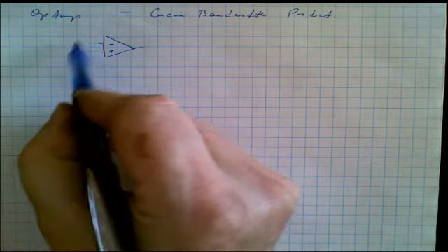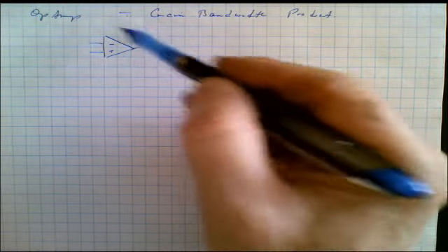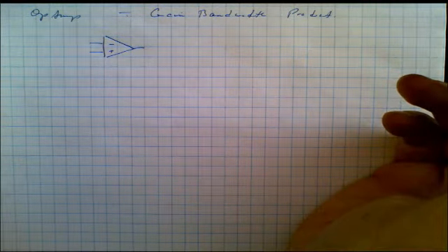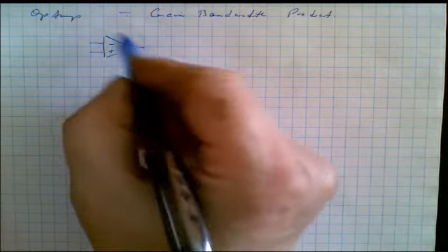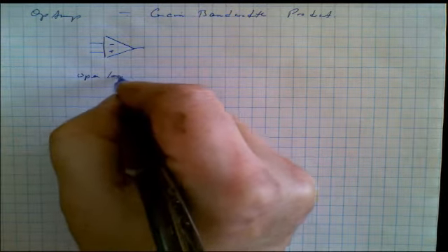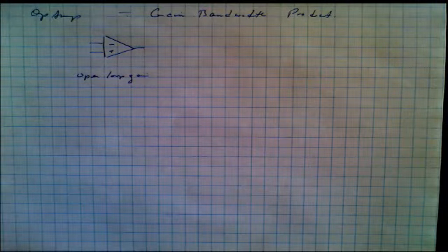There's no way you can tell exactly what the gain of this circuit is. In fact, we use external resistors and particularly the feedback resistor to control the gain. But in this particular configuration, this amplifier does in fact have gain all by itself, and it's typically very, very high. With no feedback, the open loop gain can be something in the neighborhood of 80 decibels or even greater.